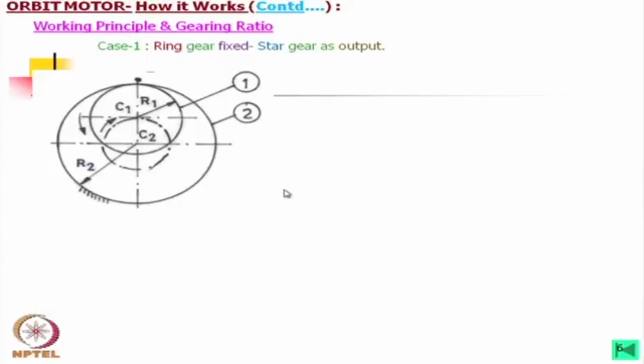What I have mentioned, the teeth here are epitrochoidal teeth, which are from the family of cycloidal teeth, and this motion is called cycloidal motion. In that case, the outer one is the describing circle of the outer member, that is in this case the envelope, the ring gear, and the inner one is the describing circle of the inner member, that is the star member.